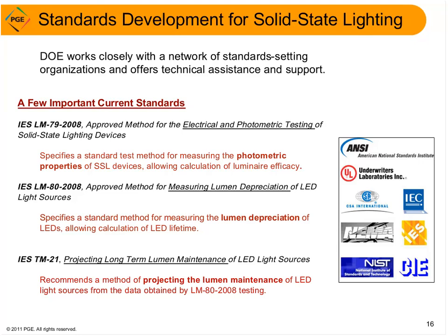This is kind of a busy slide, but I wanted to show you this because I want to emphasize that standards and technical support are crucial for the development of solid-state lighting. Many of you may have heard of LM79, and this provides a standard testing method for LED products. But keep in mind that just because a product was tested according to LM79 doesn't necessarily mean it's a good product. It only means that it was evaluated properly.